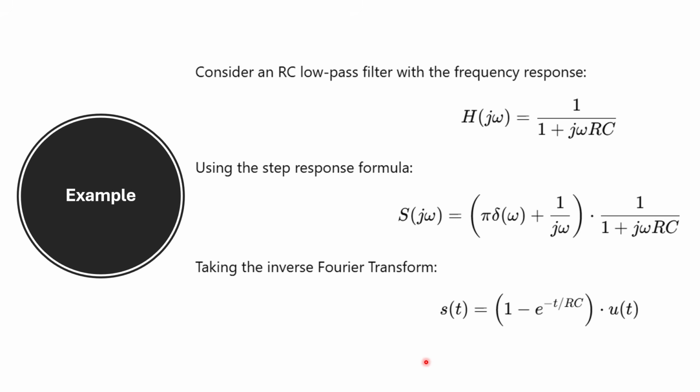In this manner you can get the response for any input; you only need the input. Replace the input here, and if you have the frequency response of that function, replace it there, then multiply and convert back into the time domain, and you will get the response for that particular input, right? So this is exactly the way to get it.